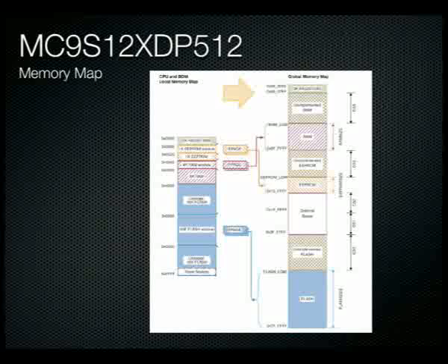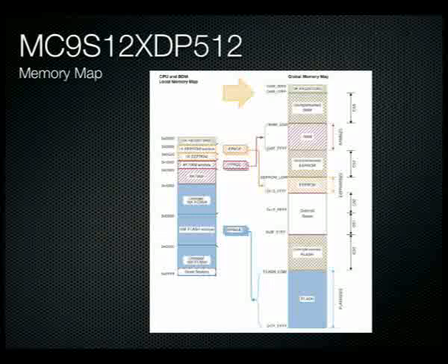Okay, and that's primarily the reason why we have our vector table mirrored into the next section that we can write to, which is from F7. So F700 to F7FF is the next writable section of flash that we can use, and that's why we put our interrupt vector table at that location instead of in the top 2K write protected chunk of memory.